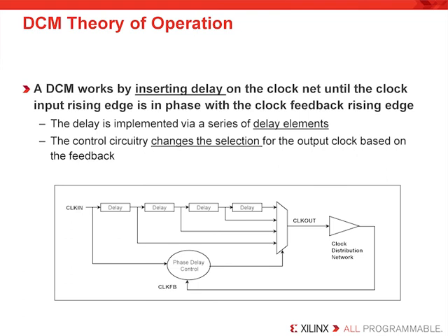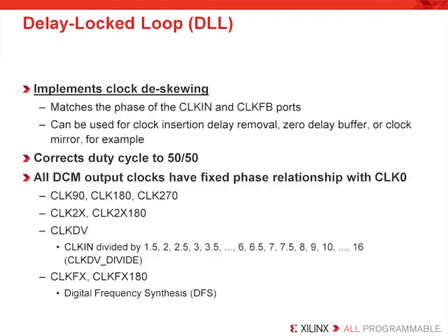But I'd like to point out as well, though, that again, being that this is a digital implementation with a fixed jitter, not all telecom applications can actually tolerate the jitter. So it's important, if you're not certain, to check your actual data sheet or user guide and make certain that the jitter characteristics of the DCM and what you select with the architecture wizard are compatible with your circuit.